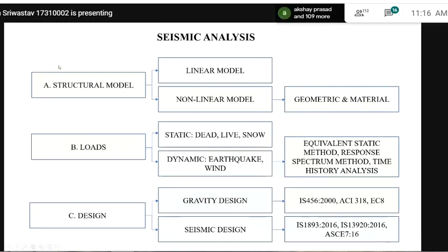Now, once the structural model is prepared, let us consider a person has given you a plan for designing a building. He wants his building to be designed. Based on that, you will create a model, maybe in any analysis software, and then after that, you need to know what kind of loads are going to act on the building. It depends upon the region which you are considering. If it is a region where snowfall is very extreme, you need to take that into account. For example, if we are designing for Siliguri, we may not require this snow load.